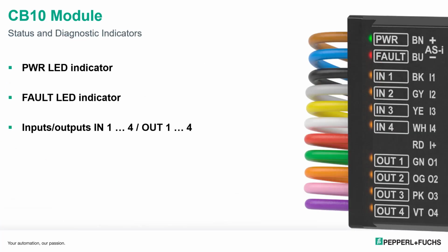And of course, the CB10 module is easy to troubleshoot. It's got LEDs for clean installs. It lets you know if the voltage is okay. It lets you know if an address has not yet been assigned, if there's a communication error, or an output overload. And it gives you details about the inputs and the outputs. The competitors I've seen do not offer this diagnostics with LED information.